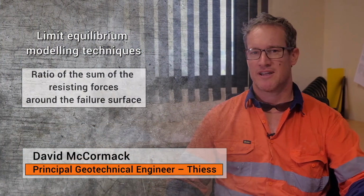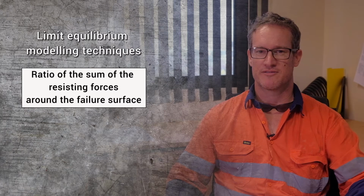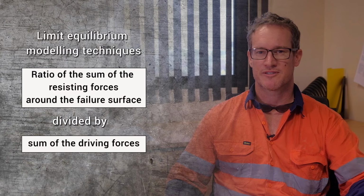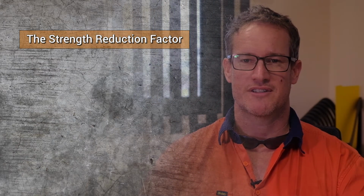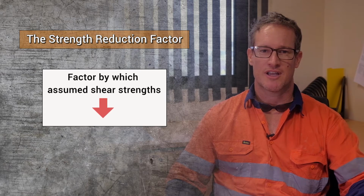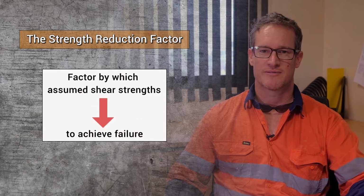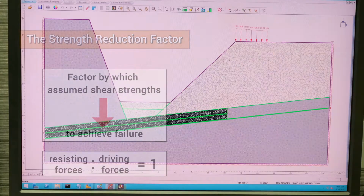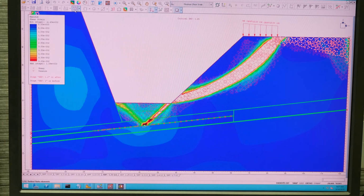Factor of safety typically relates to results generated using limit equilibrium modelling techniques and is the ratio of the sum of the resisting forces around the failure surface divided by the sum of the driving forces. The strength reduction factor is often interchanged with factor of safety, but by correct definition is the factor by which the assumed shear strengths must be reduced in order to achieve failure in the model. That is when the ratio of resisting to driving forces equals 1